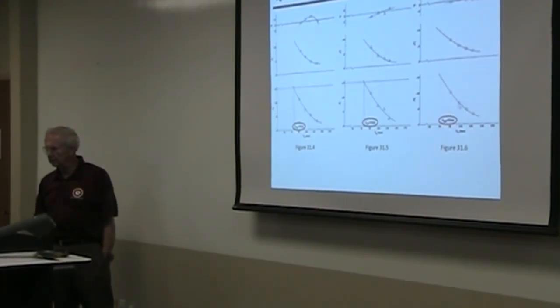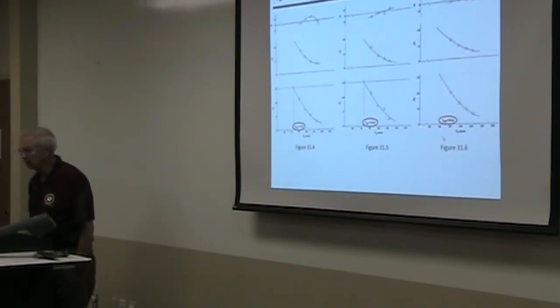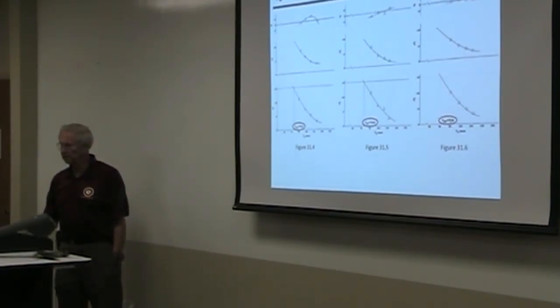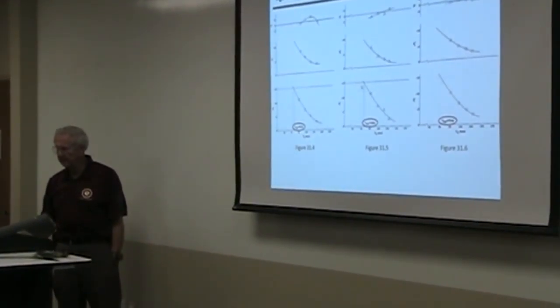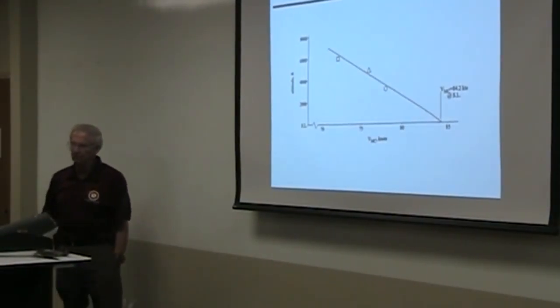Notice this one I held pretty good, not much better than that one. And notice that as we changed altitudes, the VMC tended to decrease, until here we had 72 knots. Then we take these data here and we plot them up versus altitude, okay, and then extrapolate to sea level.